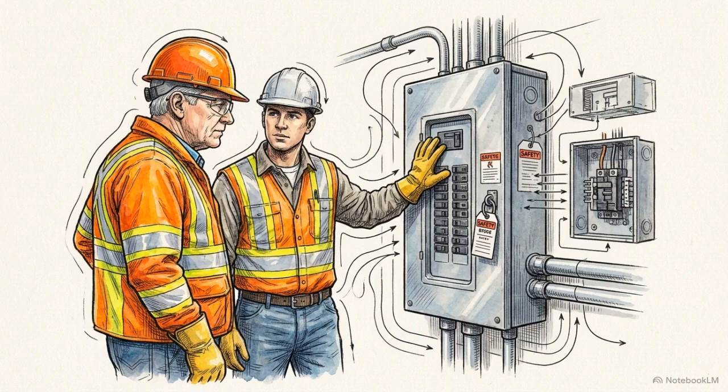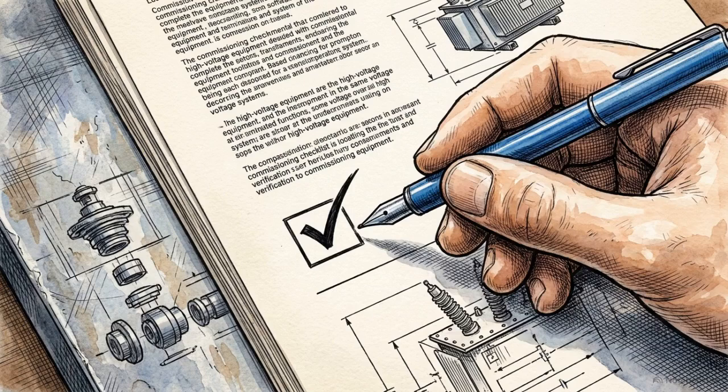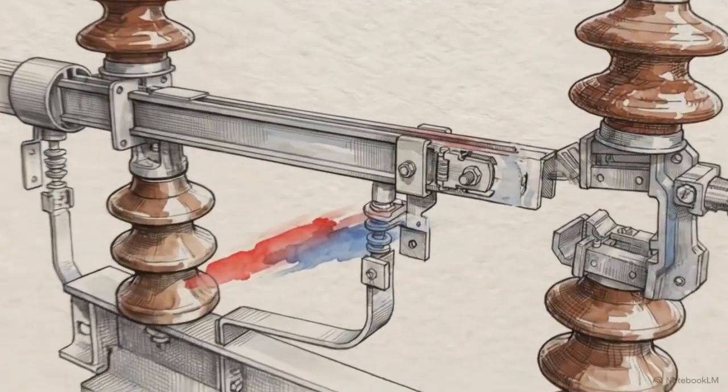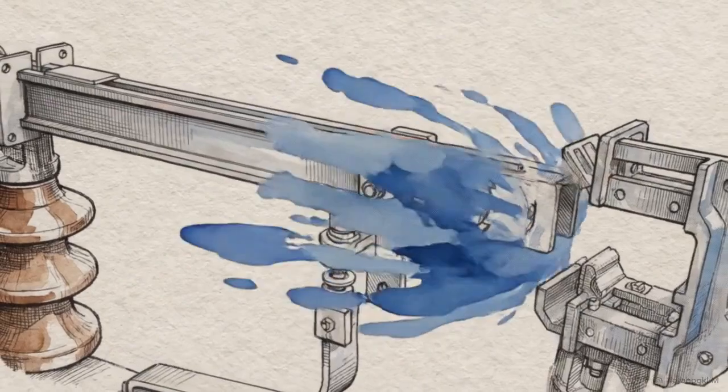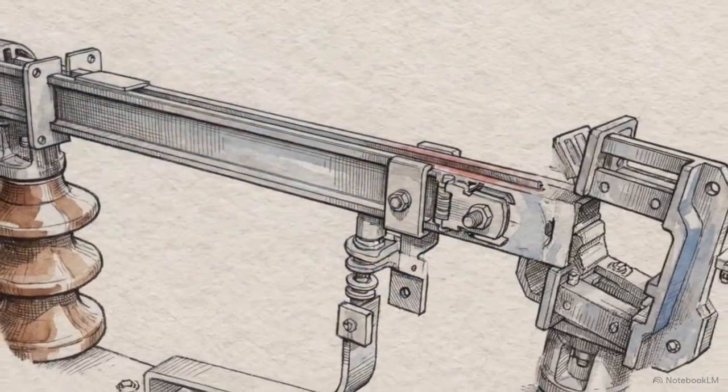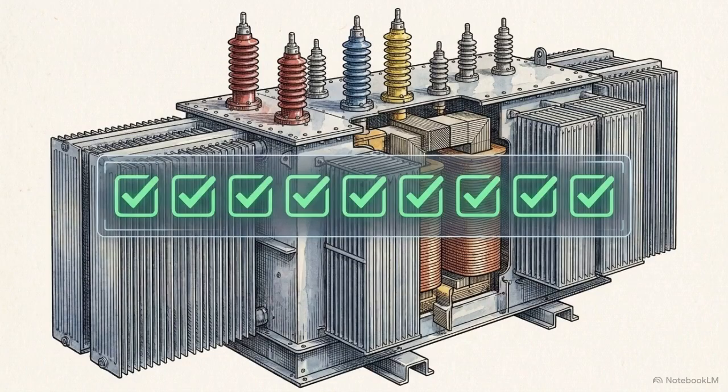All temporary forcings, bypassed trip contacts, and test alarms must be formally cleared and documented. The final witness signs off on the procedure only after full physical confirmation that normal automatic operation is completely restored. A shunt reactor is ready for grid synchronization only when all 9 validation layers align exactly, without a single bypass, compromise, or uncorrected variable.